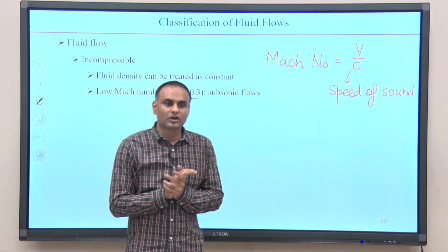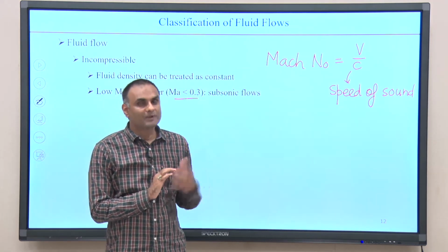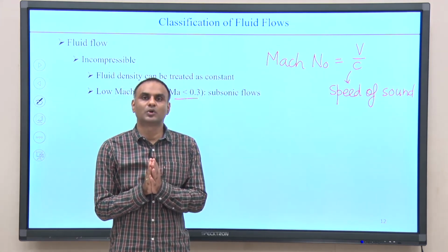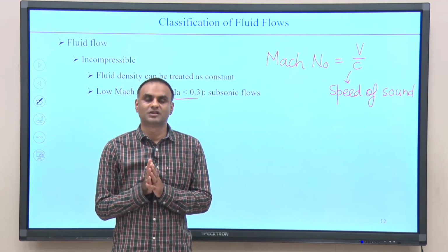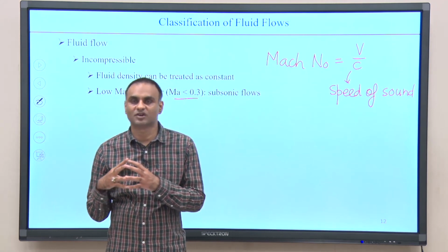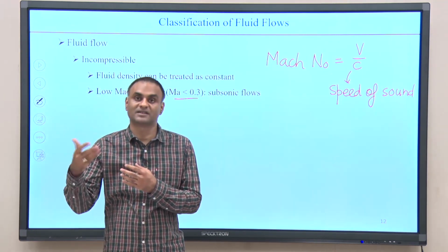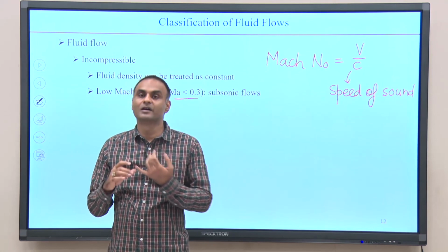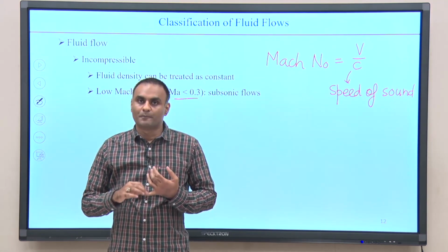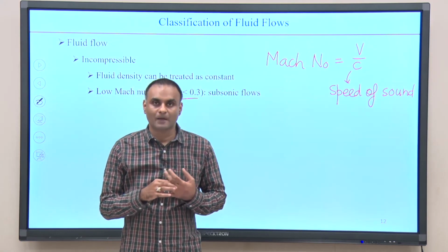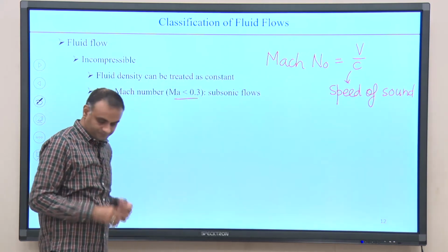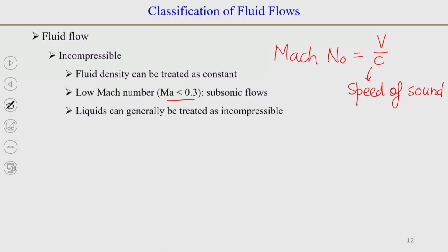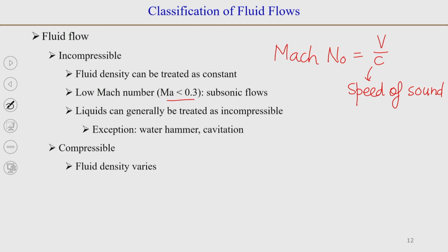Now, if we are talking about a compressible flow, then we do not know the density a priori, because the density is also a function of, say, pressure and temperature. So, for compressible flow, your unknowns will be u, v, w, pressure as well as the density. Okay. So, one needs to take into account the density variations also in compressible flows.